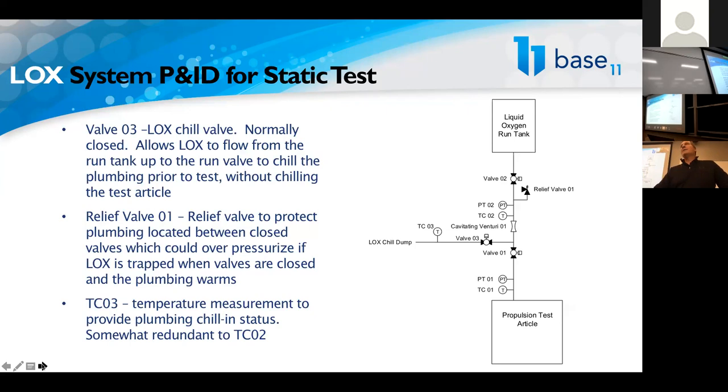Particle impact ignition hazards do not exist in LOX, but they do exist in GOX because it's a heat energy from the impact. And so in liquid oxygen, one, you're not going to be flowing fast enough to create enough impact energy, and two, it's at such a cold temperature, it's not an issue.